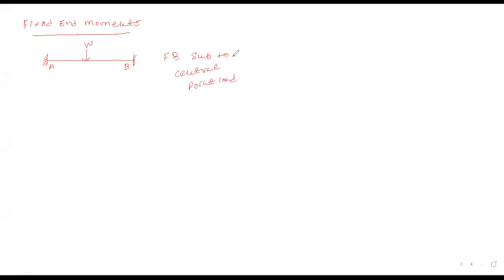Your fixed beam is subjected to central point load. So basically, for the left support, our moment will be anti-clockwise. On the right support, our moment will be clockwise. Is it okay? इतना clear है?